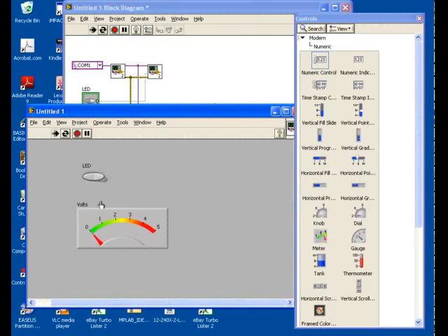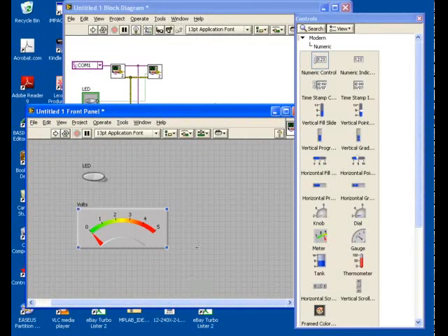So remember, the LED is hooked up to the analog to digital converter, so right now we're getting about 0 volts, and if you could see, the LED on the board is turned off, and now it's turned on. And because of the dropping resistor and the LED, it's not quite 5 volts, it's 4 volts and a good bit of change, and that's about right. And when I turn the LED off, 0, 4.5, and so on. Very simple.